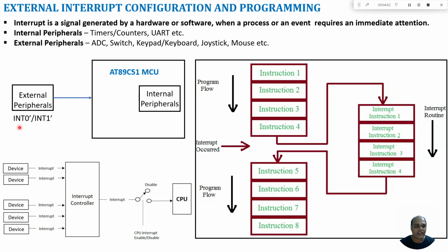Internal interrupts are the timer 0 interrupt, the timer 1 interrupt and the serial communication interrupt, both the transmission interrupt and the reception interrupt. Since it supports 5 different interrupts, the interrupts can come at any time. If 2 or more interrupts come simultaneously, then which interrupt the CPU needs to execute the program for needs to be determined.